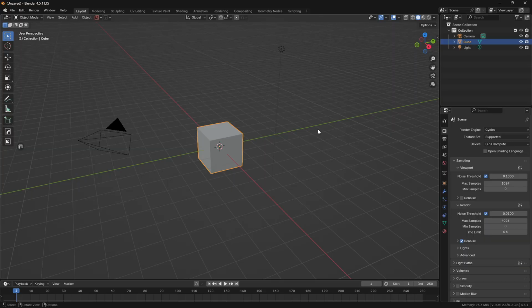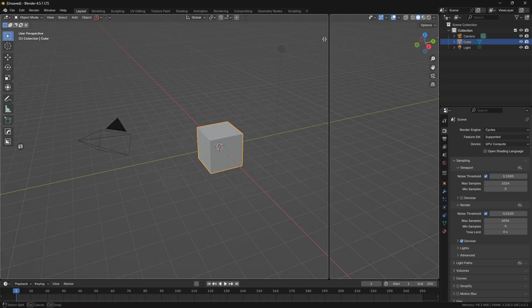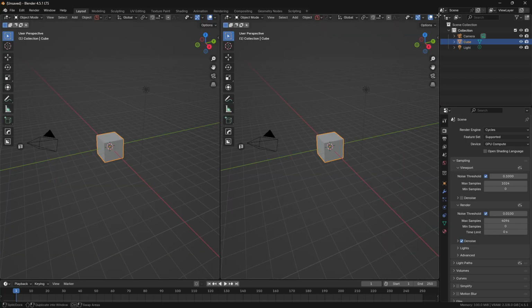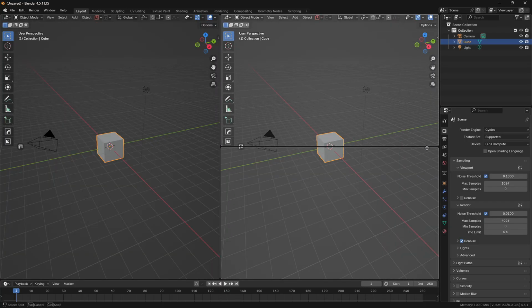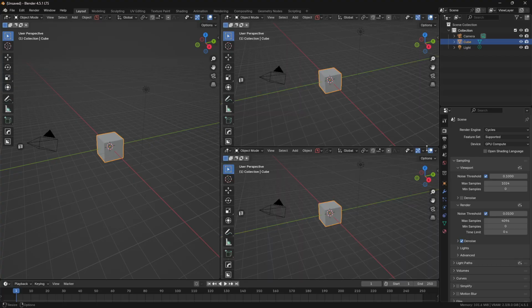To create a new workspace, go to the very corner of any window. Your cursor will turn into a crosshair, plus. To split, click the corner and drag inward. Dragging left creates a vertical split. Dragging down creates a horizontal split. This allows you to turn one window into 3 or 4 separate editors.